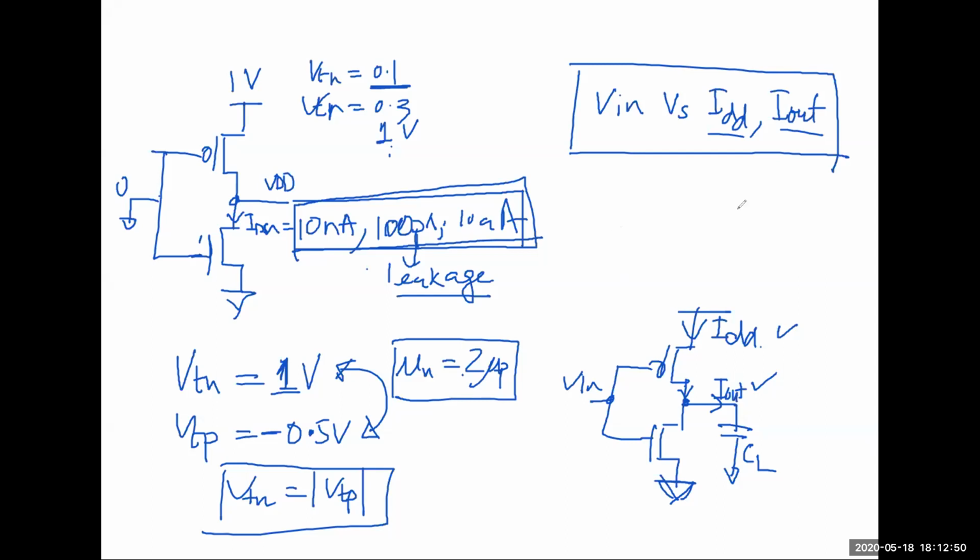For example, Chandan, as you said, saturation is like a current source, and you have the CL. If this is a current source and you have a capacitive load, how should this voltage look? For that region of operation, you say this is linear or whatever it is.